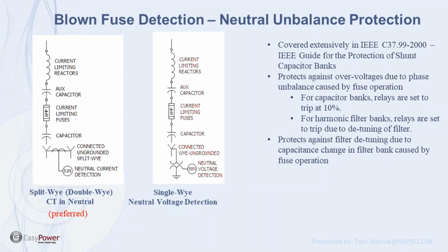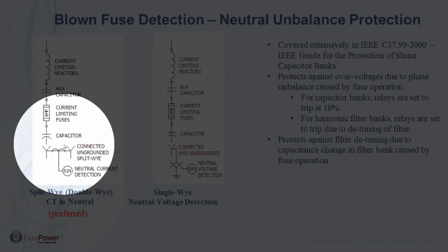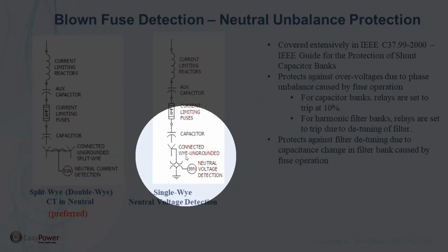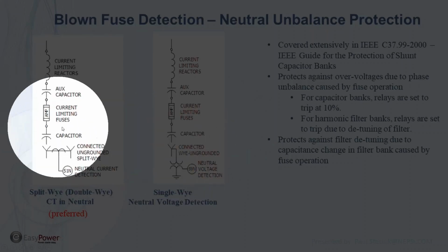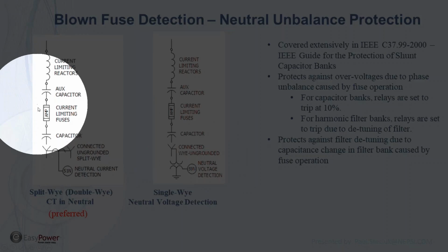Capacitors need to have some type of protection. The typical protection is blown fuse detection. We show that here. We have a neutral unbalanced protection system that's pretty standard, but we can also do fuse sensing here and check for the fuse itself.